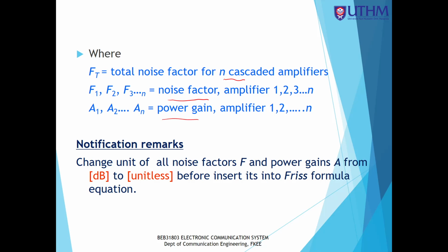The one below is important. Remember, make sure all the parameters inside the Friis formula are unitless. They cannot be in decibels.